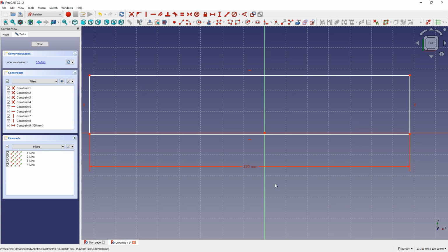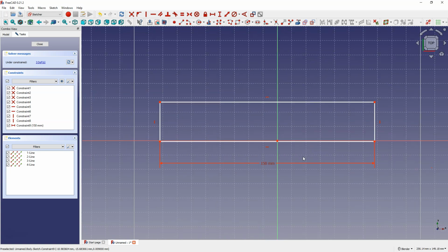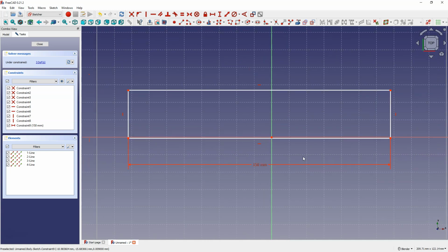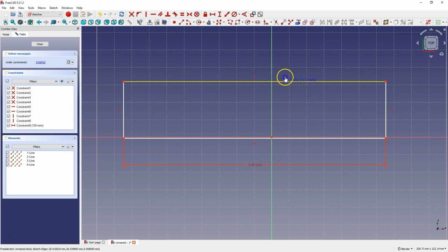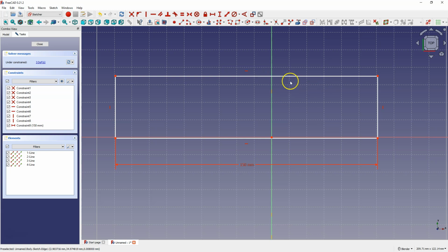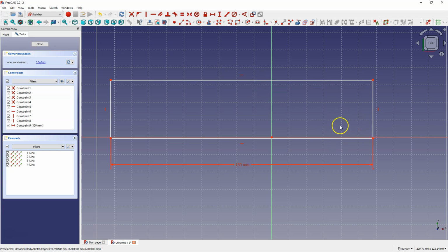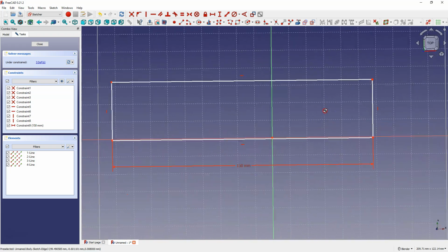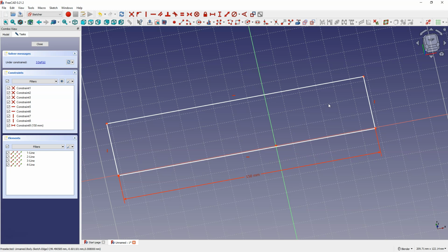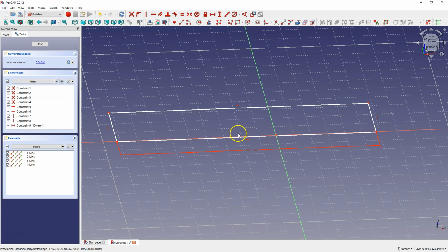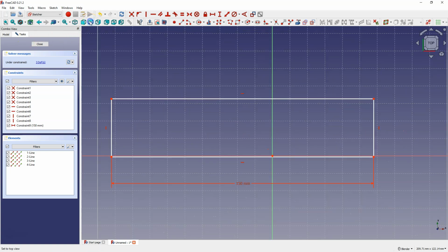And here I'll go back to navigation for a moment. Rotating the mouse wheel, we can zoom in and out of the view, and if I grab some geometry with the left mouse button, I can move this geometry, and in this case I can also change the position of this rectangle. Okay, here it can happen that you accidentally press the mouse wheel, and pressing the mouse wheel and moving the mouse rotates the view. But here we can easily return to the top view. We simply use this navigation cube and select top view here, and we can do the same by selecting one of the standard views.